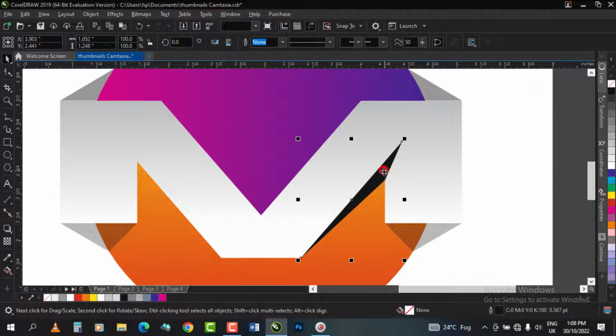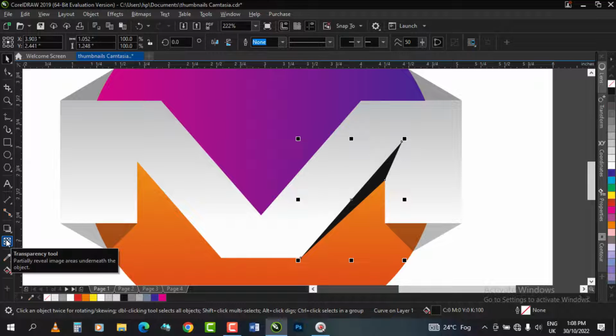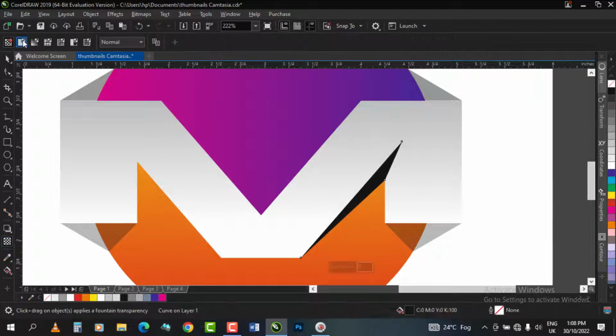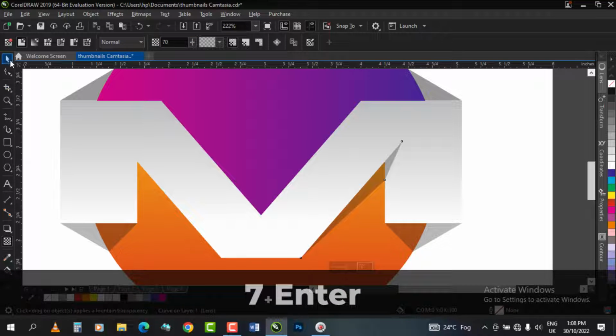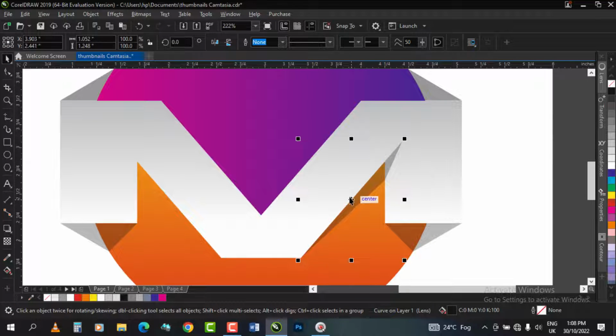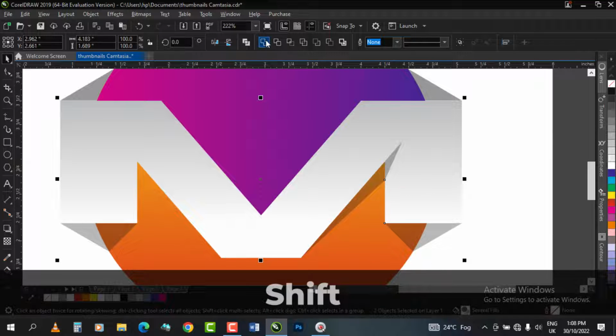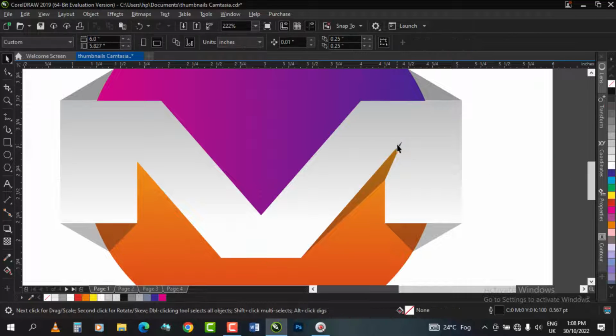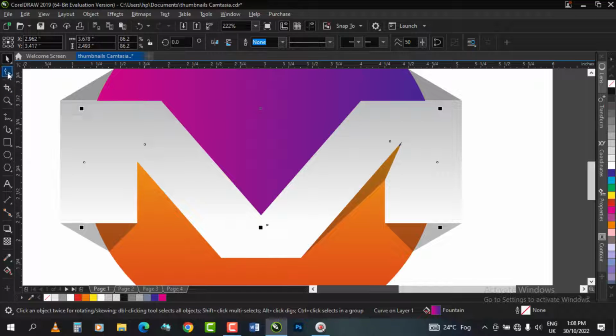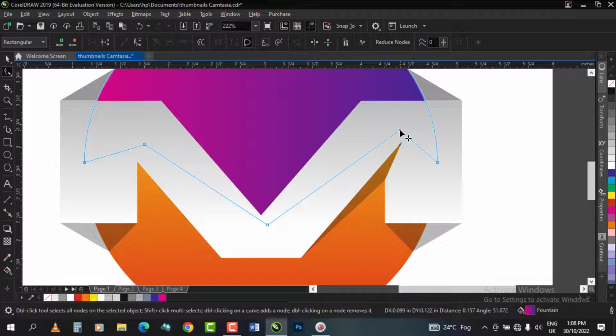But now there is an intersection over here after applying transparency. So you want to select this, hold the Shift, select this, and trim to get rid of that. But you see that blue is coming out, so you gotta take it up. See that?